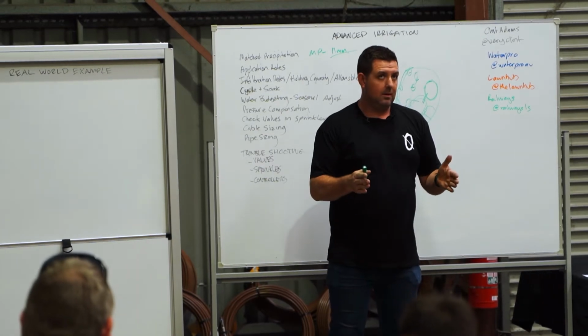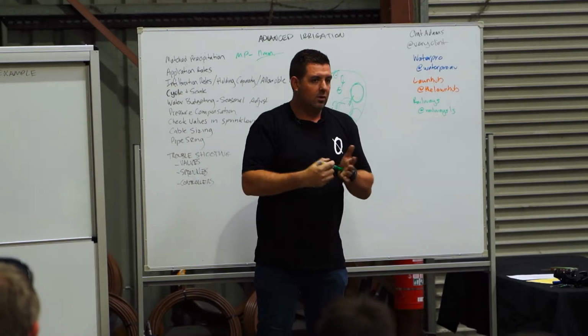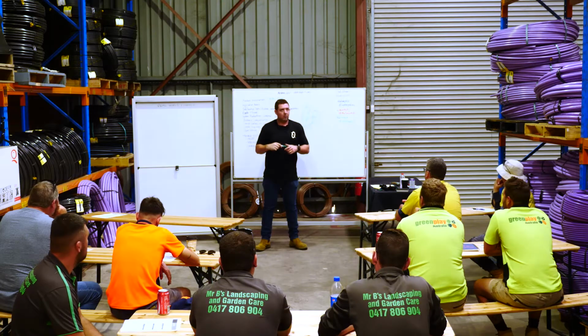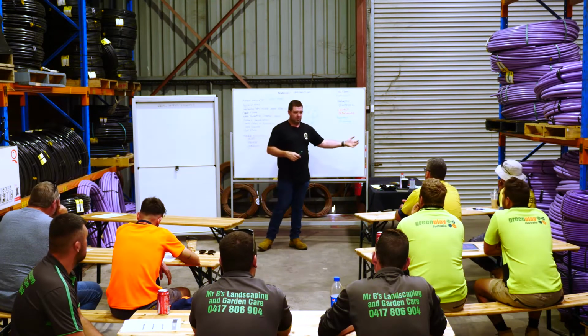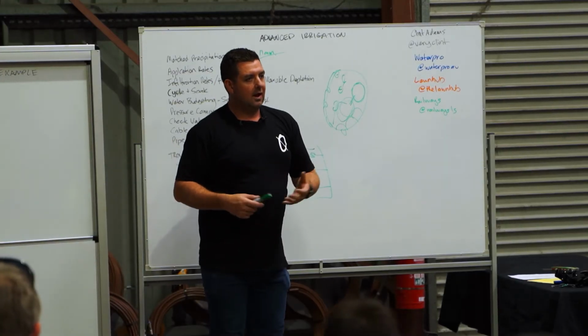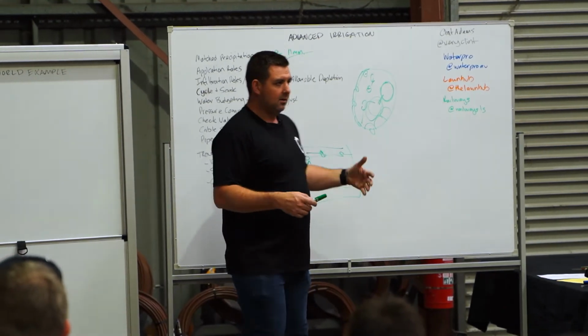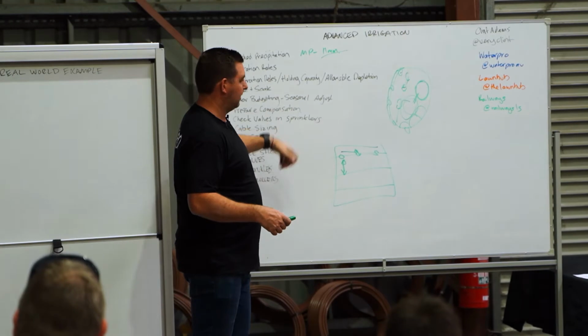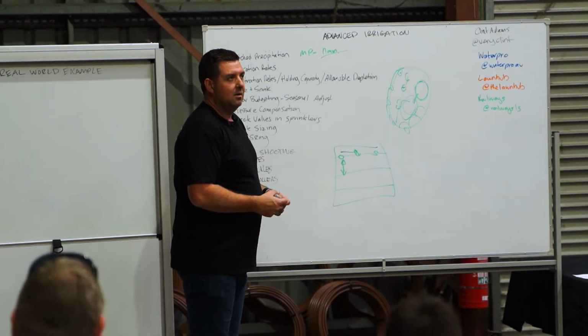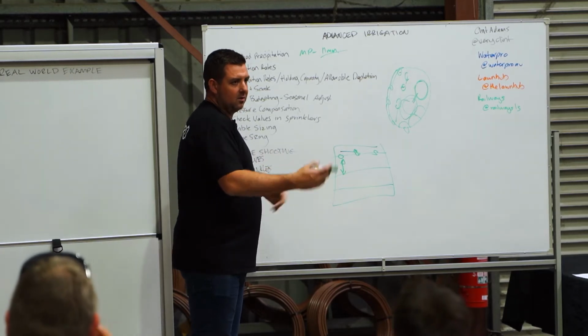So it's important for you guys to think about your soil profile and your soil types when you're choosing the spacing. But even in situations where it's specified for you, it's often only specified because it's been stolen from a document that was stolen from another document that was stolen from another document 20 years ago, and they haven't changed the document. So we're probably more likely to stand up and say, hey, this isn't right, we think we could change it. Most people just go with it, and then they wonder why there's flooding or squelching or whatever, because through that whole journey no one's actually stopped and said, hang on, is this right? It's just because they used to do it.